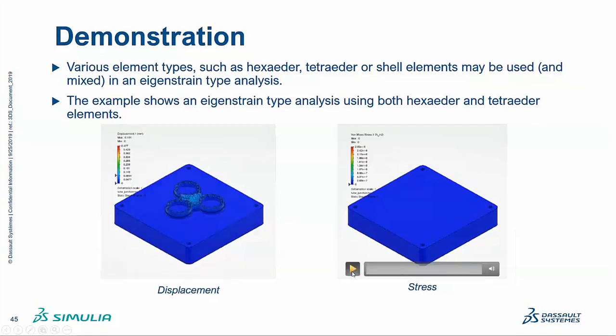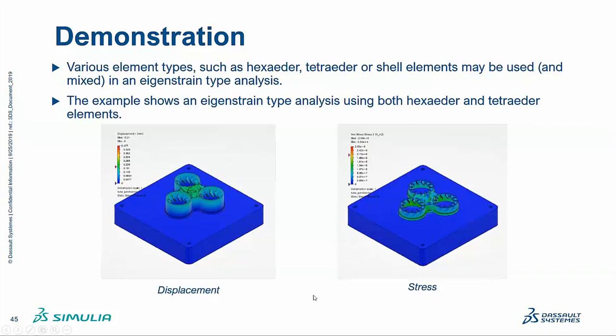In our software, we have the opportunity to use other kinds of elements. We just talked about finite elements, and here's a simple example showing that we can do the same kind of structural analysis using the eigenstrain approach with non-voxel meshing techniques. So we can use tetrahedral elements or hex elements adjusting to the actual structure. We can use shell elements if that is needed for small support structures and so on, and get a somewhat better representation of the field, again with the eigenstrain approximation kept in mind. But as we can see, the result is much closer to the actual structure.